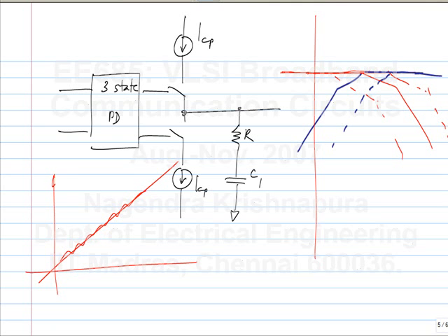So this is phase. So this noise is known as phase noise. Okay. Now, in a phase locked loop, given the phase noise of the input and the phase noise of the VCO and maybe noise in other components, you can calculate the phase noise of the output by using all these transfer functions. Okay. It's a linear system, so it has some contribution from the input, some from the VCO, some from the internal components. You sum everything up and you finally compute the phase noise.